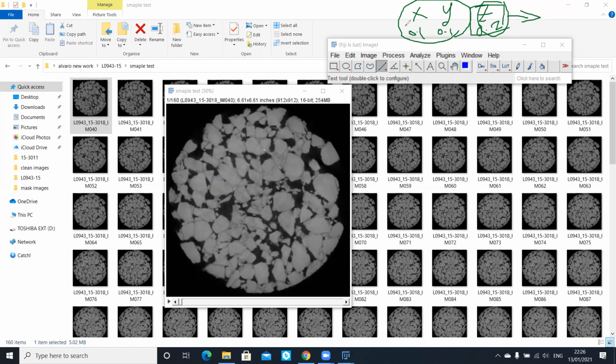For example, he gives me from the operator that the XY is 0.1 millimeter per pixel. Each pixel equals 0.1 millimeter. So when I do a 50% rescale, this one needs to be changed. It will not be 0.1 millimeter, it will be 0.2 millimeter for every pixel. I need to change the number I take from the operator for X and Y for the resize. That needs to be in your head before we start to put the size.